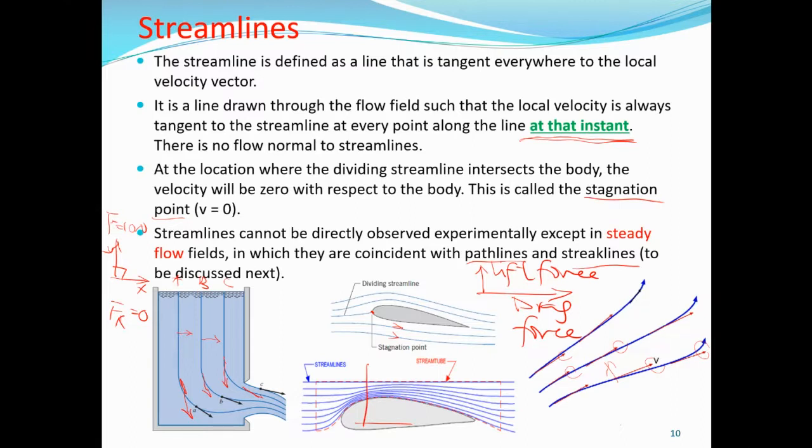So this drag force, depending on the geometry, you can see this airfoil may exert little drag because only this will hit it, assuming the body is shaped this way. So many streamlines will become dividing streamlines, thereby exerting drag. That is why an airplane is shaped like this, to allow smooth flow of air around the wings.